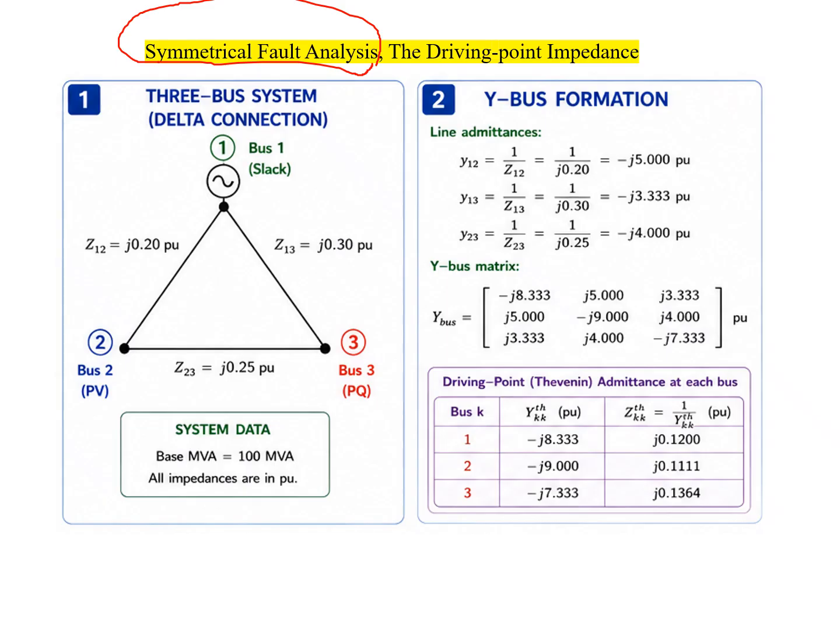In a power system, we classify the buses into three: slack bus, PV bus, as well as PQ bus, based on their role in a power system. So you can remember what we try to say for slack bus. For the slack bus, we have fixed voltage and voltage angle, whereas the power, both active and reactive, will be calculated based on the power mismatch.